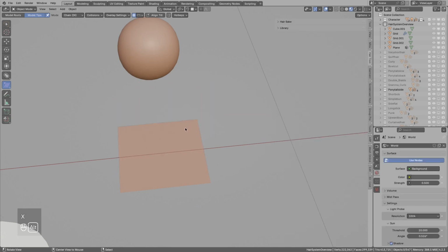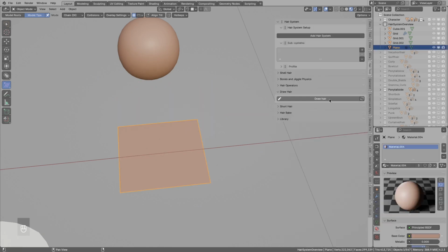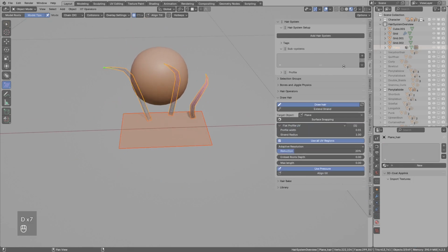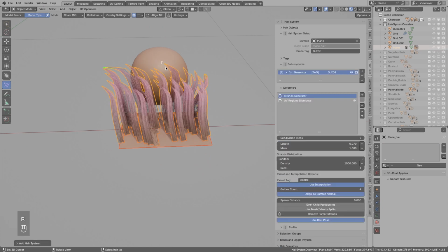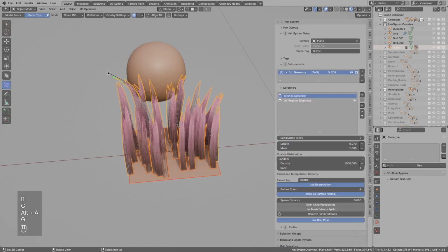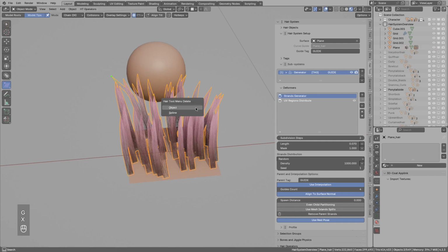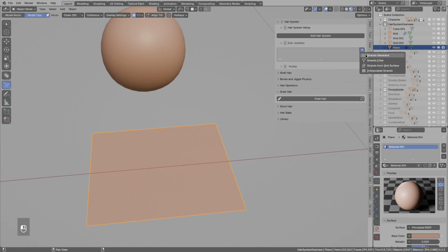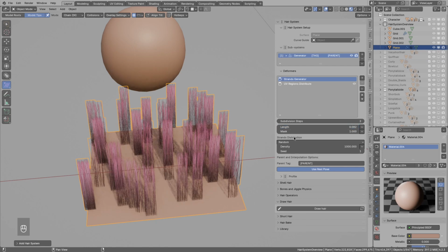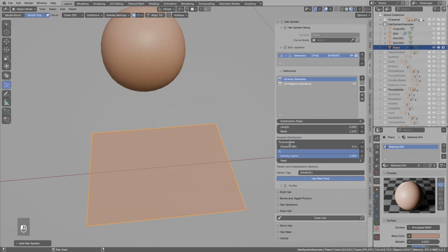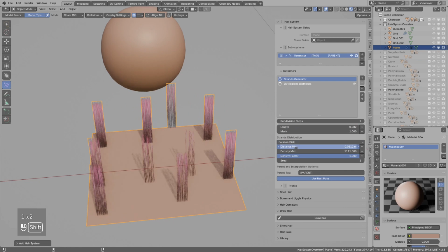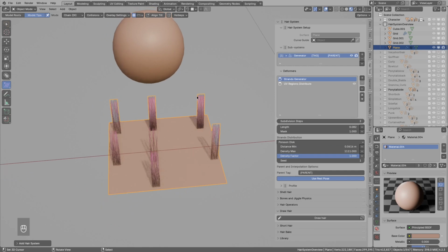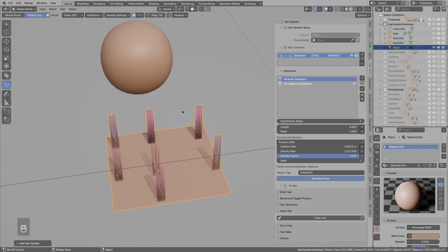So instead, what I prefer to do, and the fastest way, is to just enable hair drawing, draw a few strands, and then add hair system to it, and that's it. There is also a slightly slower but cool way if I delete the hair system. I also sometimes like to add the strand generator, make this maybe more uniform, like that. And then I usually would like to bake this into real curve geometry and use as guide.